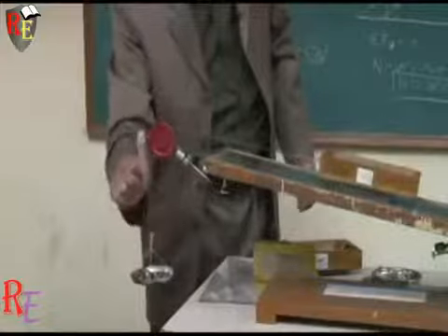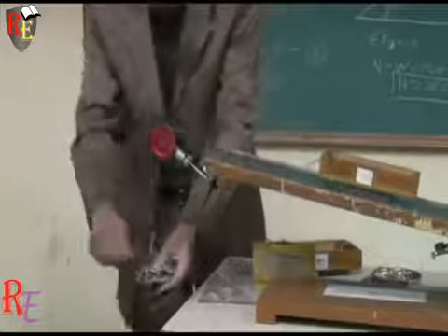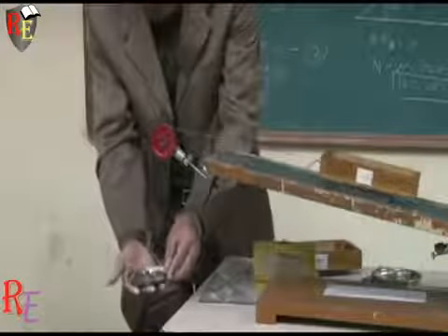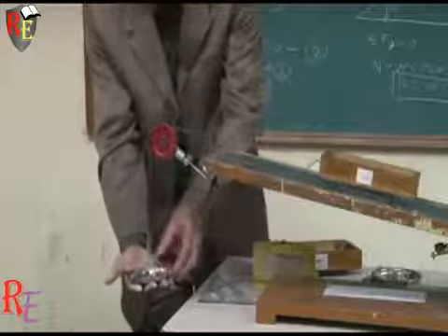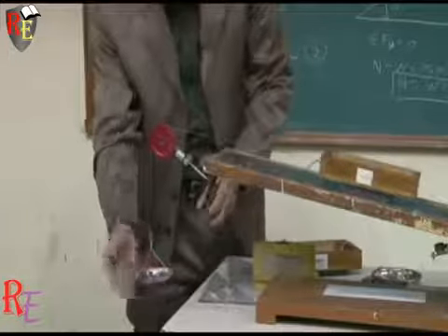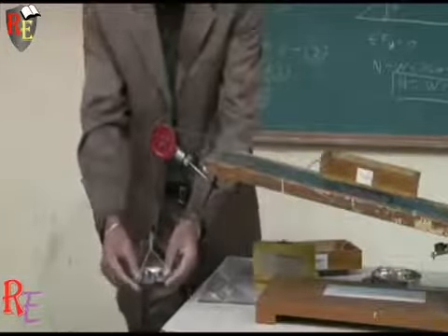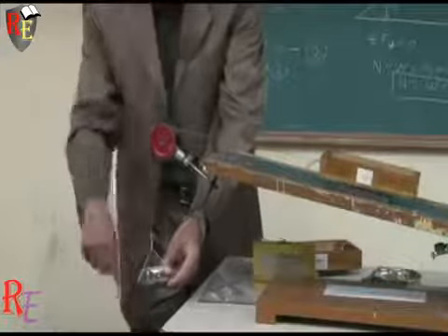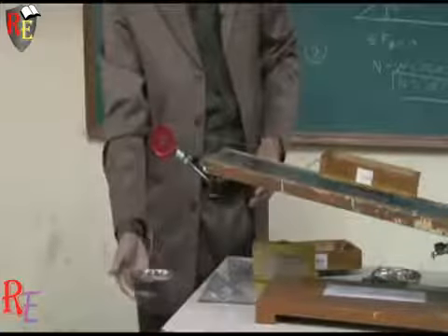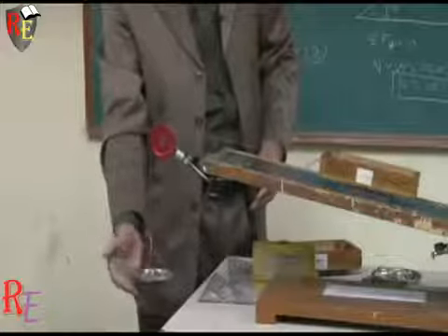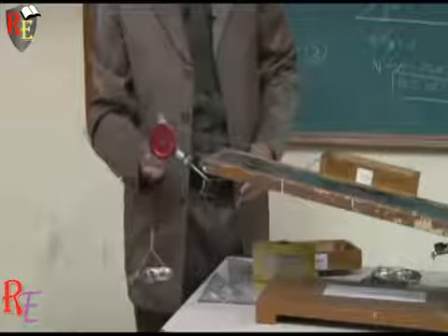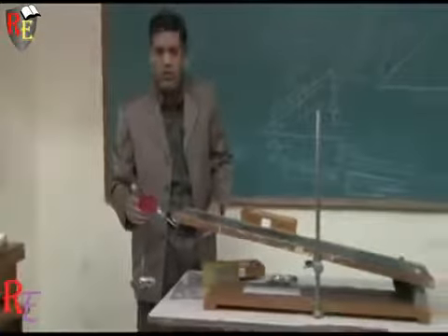So T is acting upward. The P, that is the effort applied or the load applied. This load includes the weight of this pan also, that is acting downward. Since it is not moving in the y direction, it means the net force in the y direction is equal to 0.